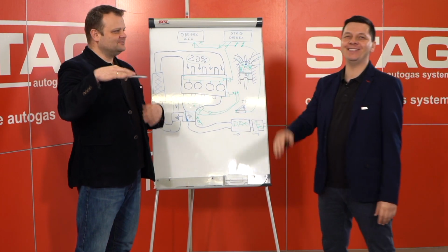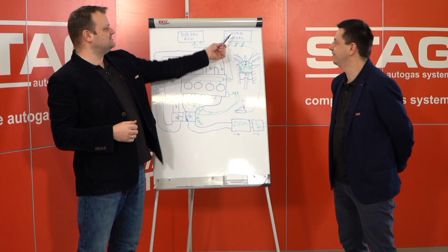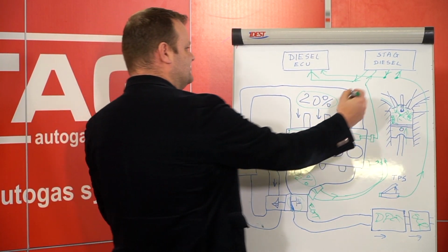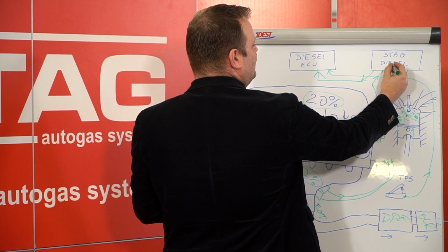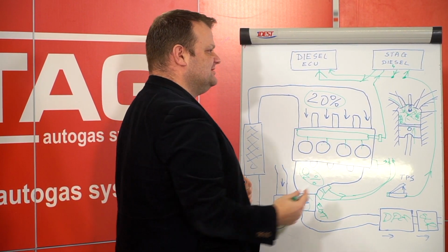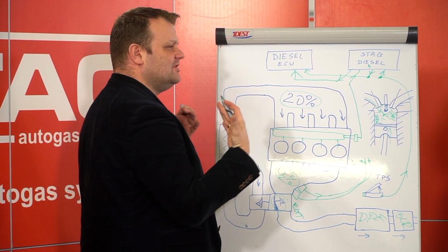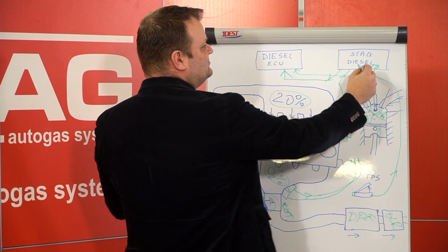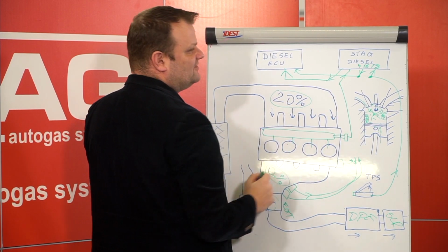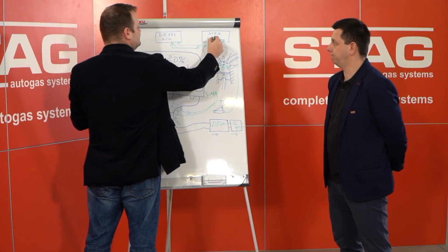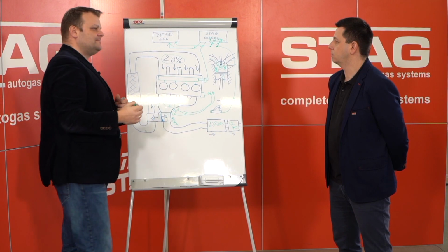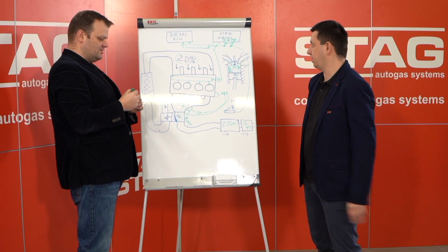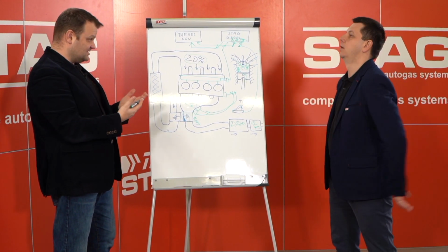There is no relation between the number in the name of the ECU and the number of cylinders. It is information about how many channels of injectors we can handle, how many injectors we can connect to the system.